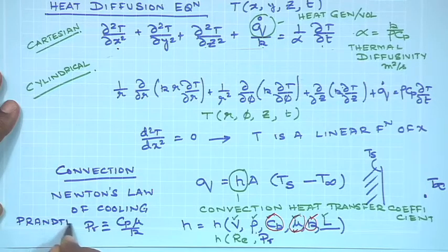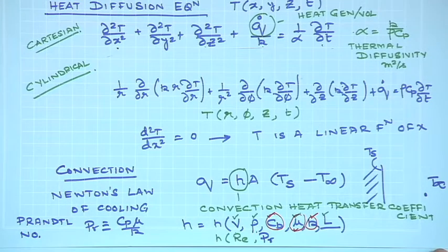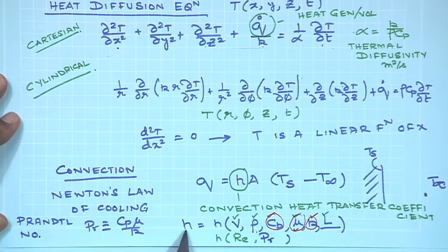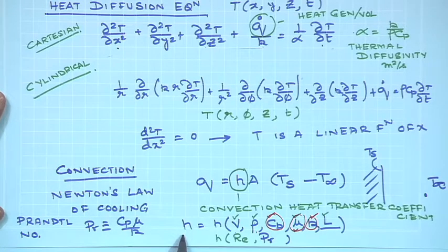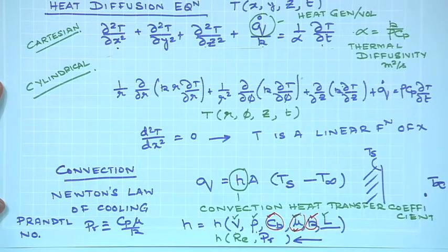One of the famous scientists who has done extraordinary work not only on momentum transfer, the concept of boundary layer, but also on heat transfer. So, most likely any correlation, any relation that you would see for forced convection, where the fluid is made to flow by an external agency, is going to be a function of the Reynolds and Prandtl number. We will see this more when we discuss convection, but right now it would be sufficient to know that